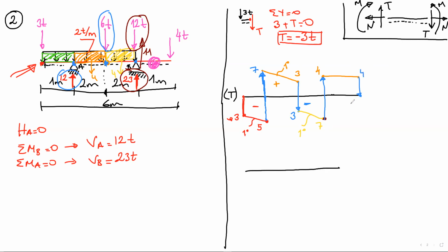So this is my shear force diagram. While I was drawing this curve, I used the point loads and their directions. And also there were some distributed loads on the system. The point load locations are critical locations because there's a sudden change on the shear force diagram.